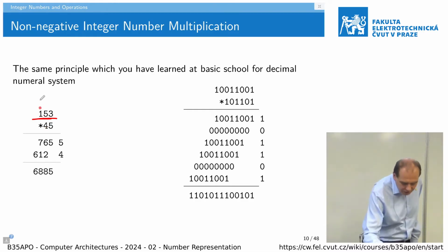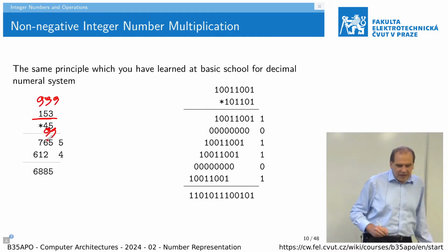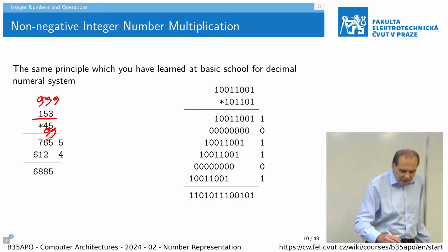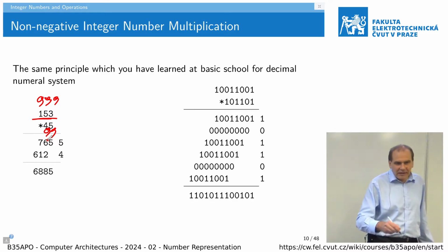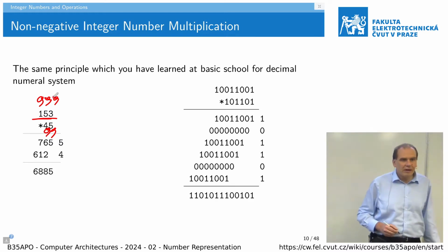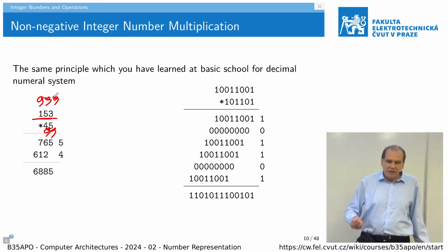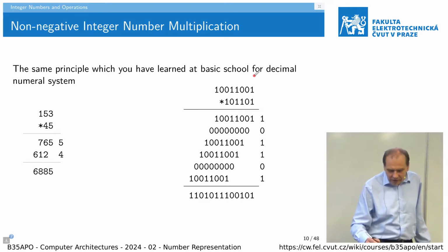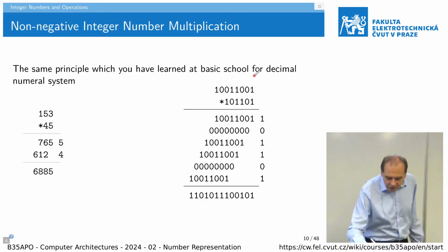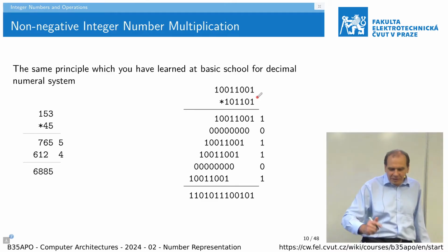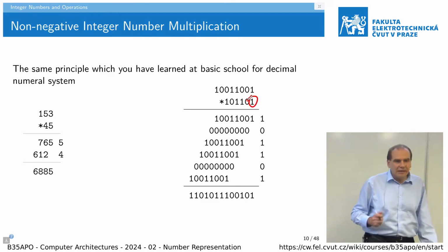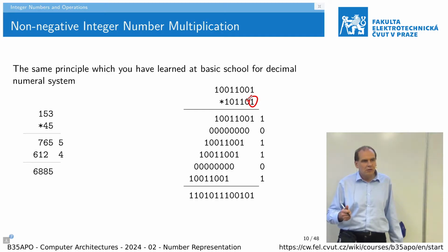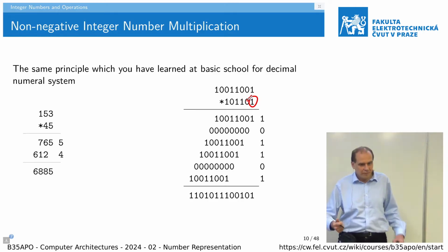If we multiplied 999 with 99, then we in fact can get something like 99899 and so on, and it would be five digits. And exactly the same problems apply to the multiplication in binary, but it is a little easier because in binary we know that multiplication by a single bit is only a logical masking. We take the value or we mask it to 0. So it is much easier.